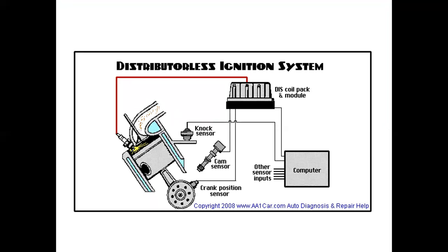So what is the main advantage of the distributionless system over the distributor? Mainly, the distributor is used to ignite the coils. That means it is like a relay, used to ignite the different spark plugs. It will rotate in a rotating format only. If you want to ignite 1 and 4, we have to go with 1, skip 2 and 3, then go for 4. It will take more time, with a difference between the input and the output condition.